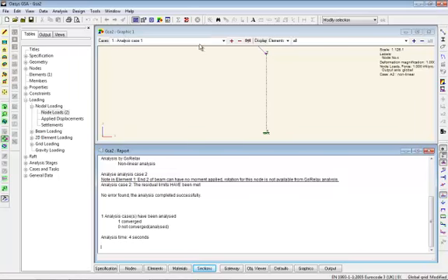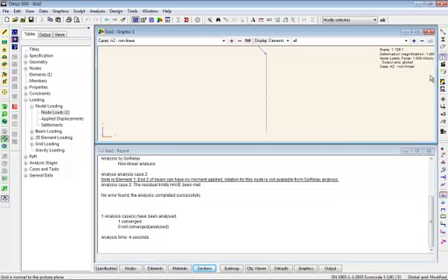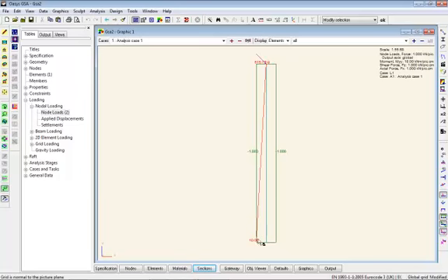And the end results of these, well, if I switch off the collection shape, moment, bending moment, shear force, axial. So the linear, which is this one here, we can see that the bending moment is 10, the axial is 1, the shear force is 1. It's all what we would expect, and the non-linear, very, very similar.